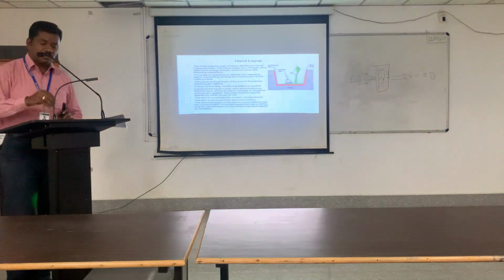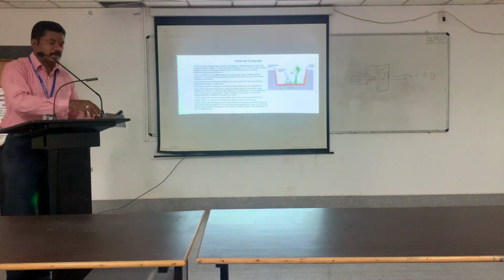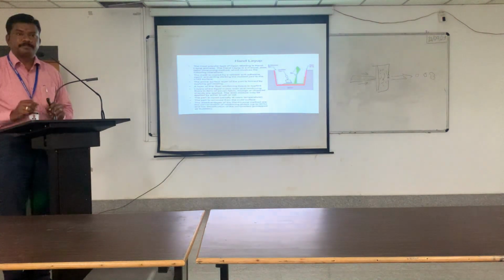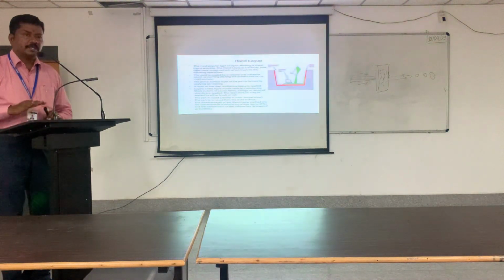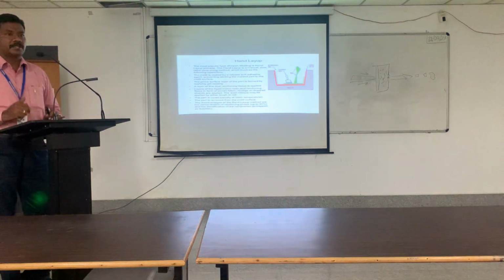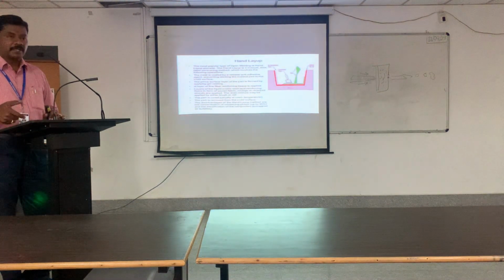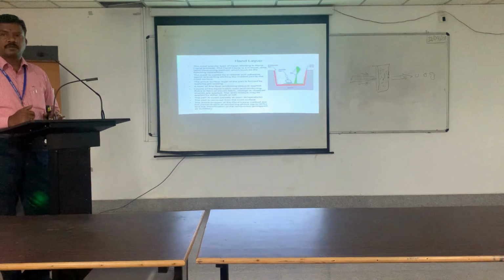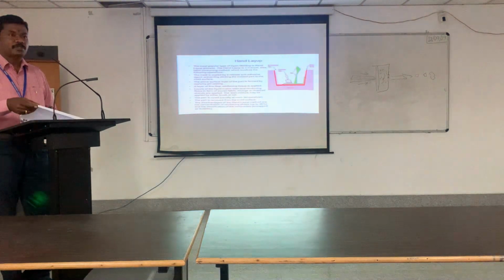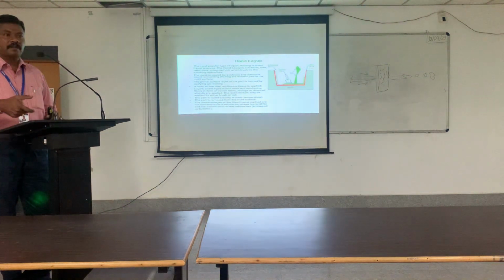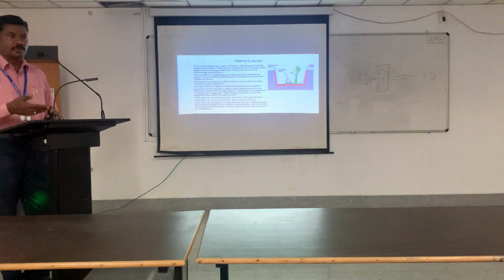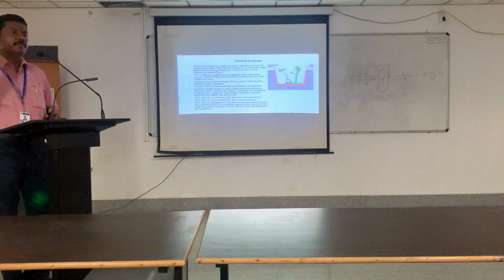Okay. Then again you have to pour the resin, you have to spread it out, then the next layer you have to place. Again you have to roll it. This has to be repeated until the required thickness is achieved. If 10 mm thickness is required, and each layer contributes 0.8 mm, then 10 layers you have to place, then the matrix thickness will also be added. Finally you will get a 10 mm thick plate.